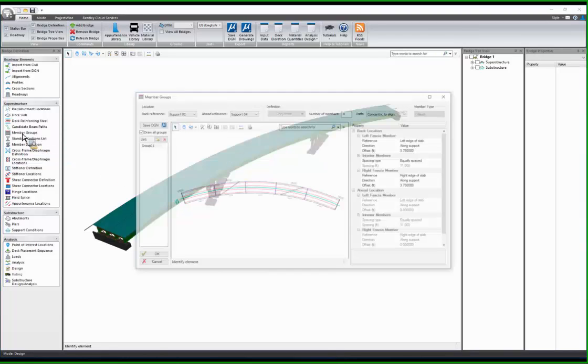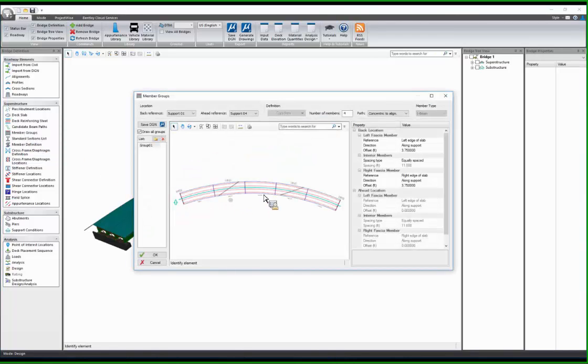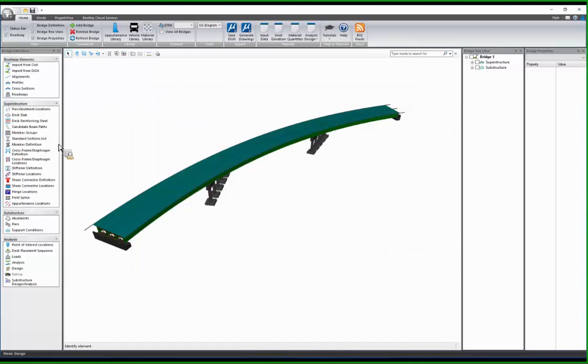And when you're defining the girders themselves, guess what? Then you have the ability to create as many groups as you want. You can define the continuity by selecting the beginning and end support conditions. And in this area right here, very nicely, there is no arrow, but I know that if I want to select something, I click on it and this appears and you select any other references or a direction or an offset. That's how we do it, okay? All right, that's nice. But then we continue.